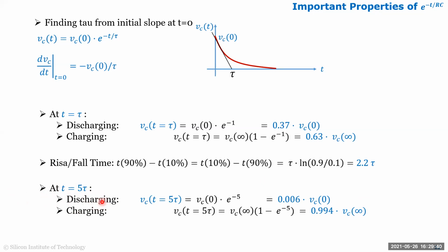and if the A to D is like an 8-bit A to D, then we say, okay, it needs to settle to around 99.94%, so allow it to settle for 5 tau, and that'll be good enough. So that tells you about your clock frequencies too. Let's say you have a delay, you're creating a clock frequency and you want it to settle to almost 99%, then your clock period will be almost 2 times 5 tau, which is 10 tau of your delay.